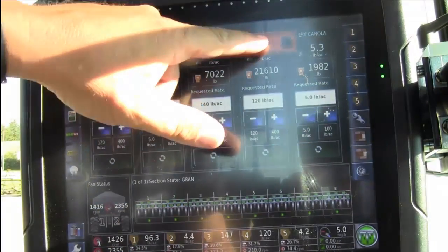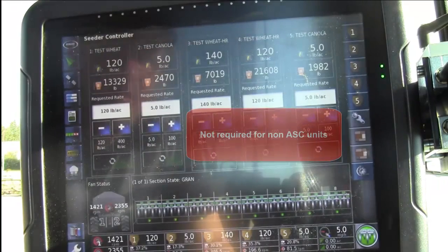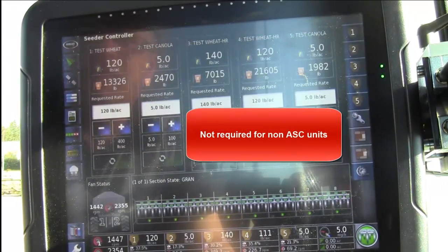At this time, you should have a partner back at the Auto Sectional Control manifold viewing the section gates opening and closing for each of the sections one at a time. Then follow the hoses going to each manifold. We'll show you that later in the video.